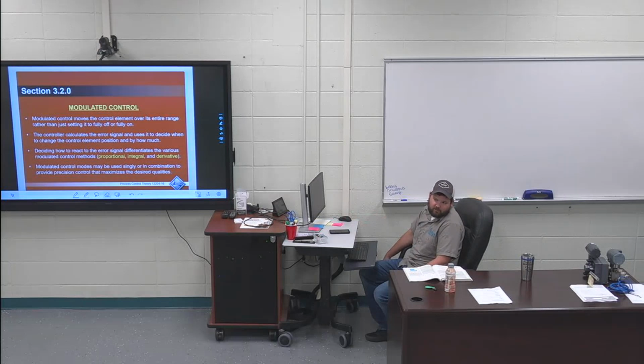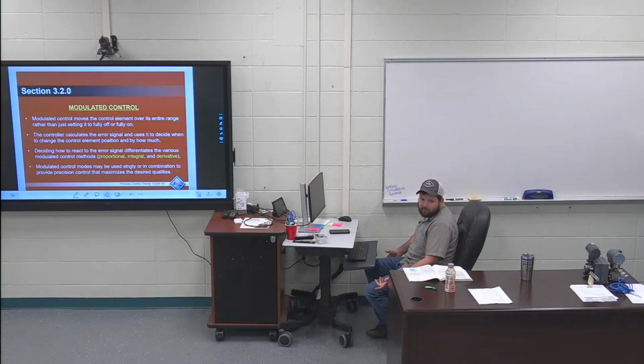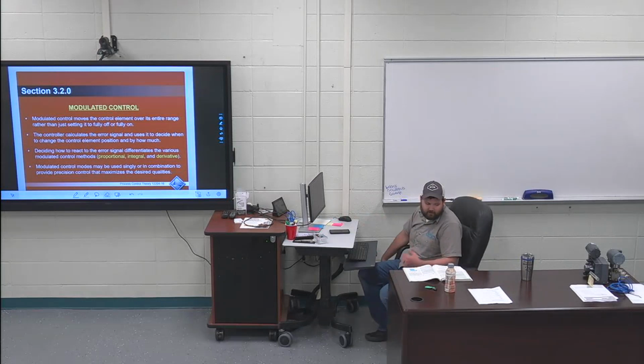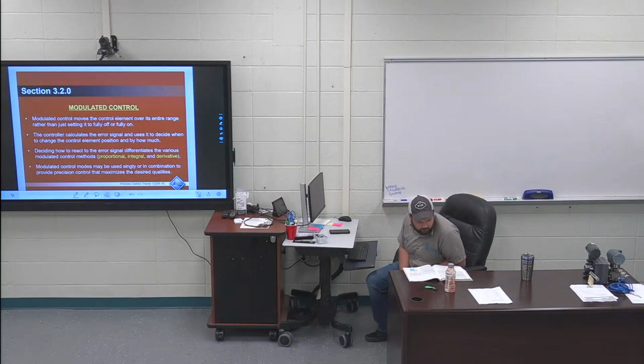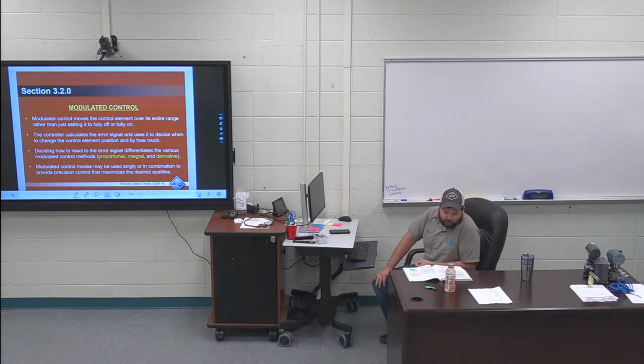You have analog or digital. Digital is on and off. Binary, zeros and ones, on and off. Analog, 4 to 20, 3 to 15. You have an actual span with modulating control for analog.